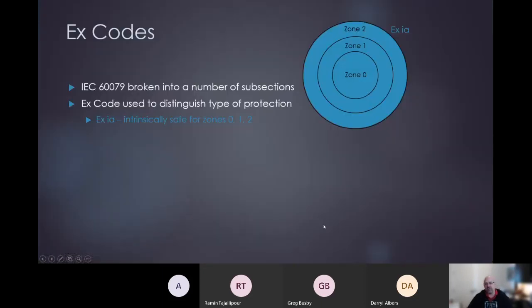So back to the certification label, one of the things that helps you identify this, it usually does say class 1 zone 0 or class 1 zone 2, but there's usually an EX code, especially when you're dealing with the 679. So it's meant so that you can look at it and understand exactly where it can be installed. A lot of ETC's products are EXIA, and that means that it is rated for zone 0. So it'll say class 1 zone 0, but it can be in any zone that's less hazardous.